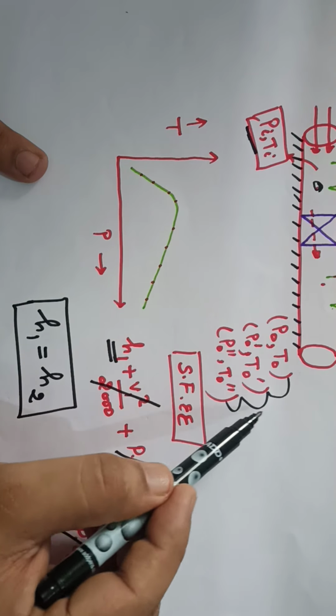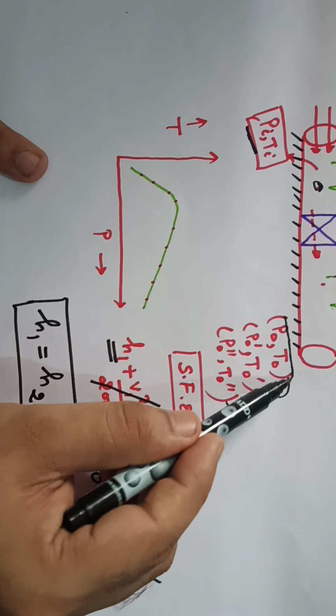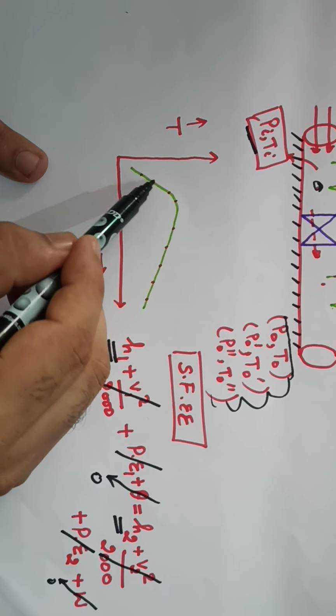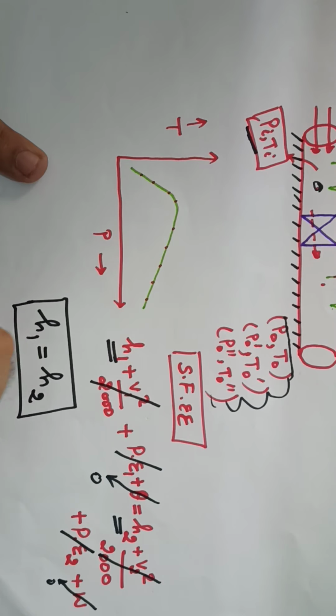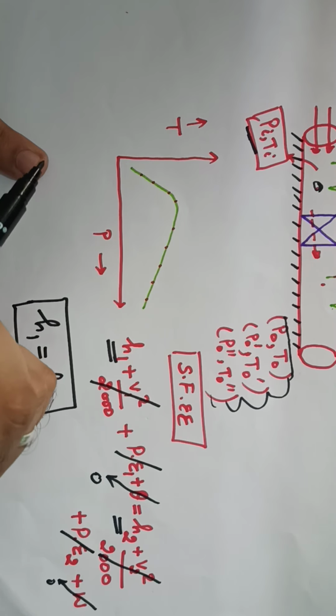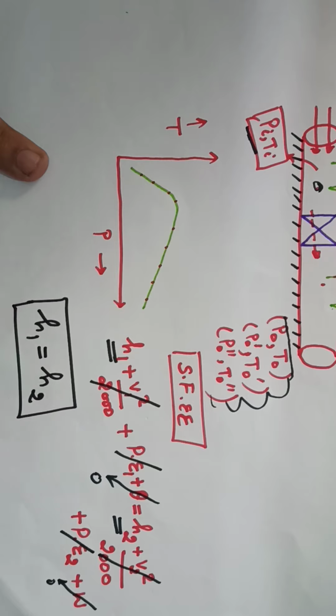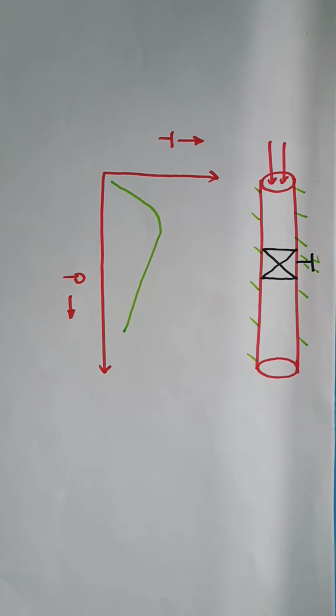And when we plot all these isenthalpic points, all these points having the same enthalpy, on this T-P plane, we get an isenthalpic curve. And the slope of this curve is the Joule Kelvin coefficient or Joule Thomson coefficient. So up to now we obtained this sort of curve on the T-P plane for fixed inlet conditions of Pi and Ti.